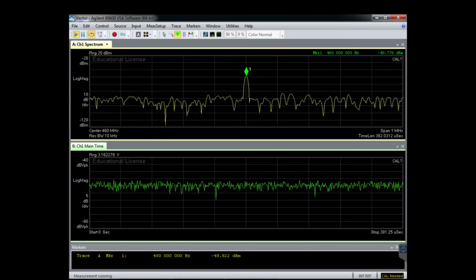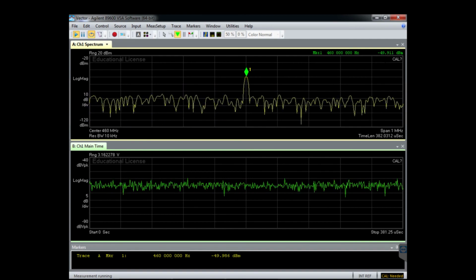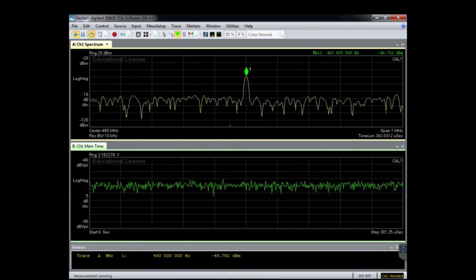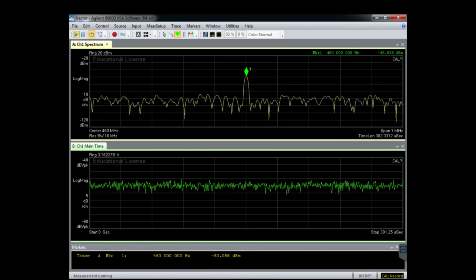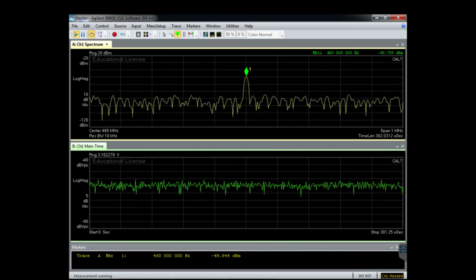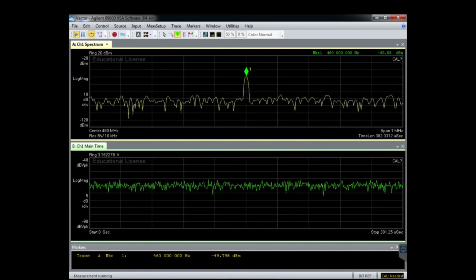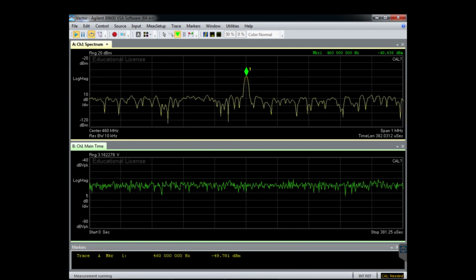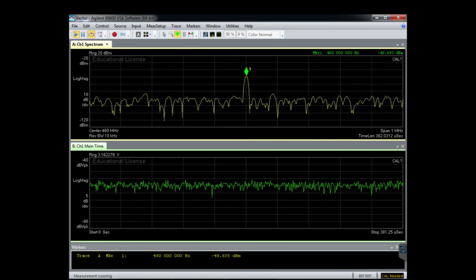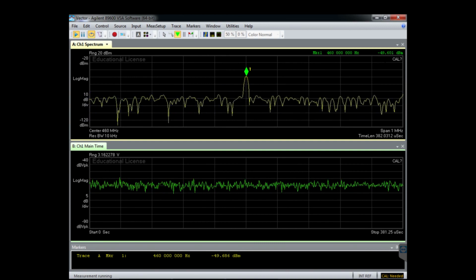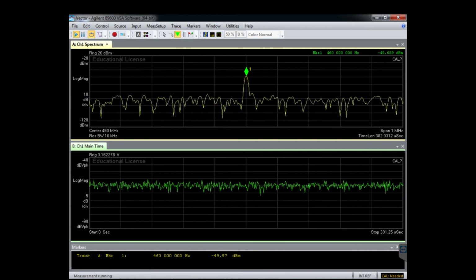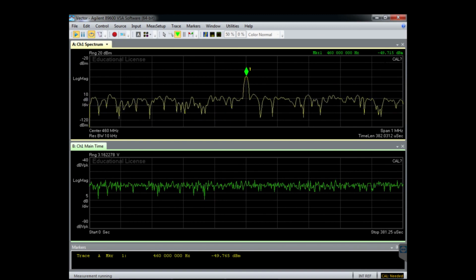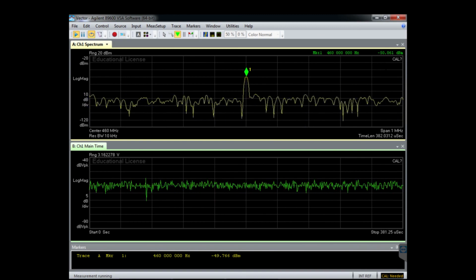And as we see here, we have a received power of almost minus 49 to minus 50 dBm, which is a significant loss compared with the wired connection. As we saw earlier, at such operating frequencies, the loss is very minor. It's just fractions of 1 dB, but that was in the case of a wired connection. If we have a wireless connection, we see that even at close distances, we have a loss that can be up to 20 dB.